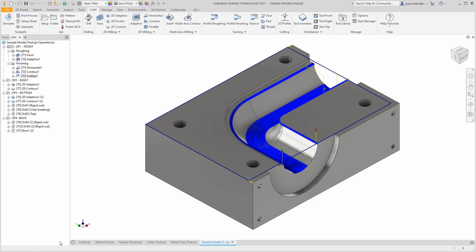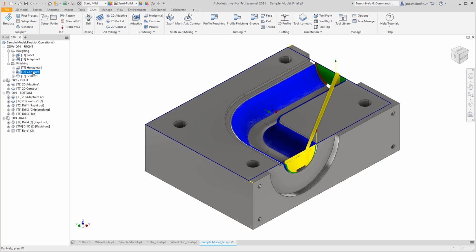So if I cancel this out, you can see that in this gray area, it's not adding toolpath. That's a steeper cut, but it is using this finishing path down here and as well at the top. So that's within those angular ranges. And the contour was what was used to do the other areas outside of those angular ranges.